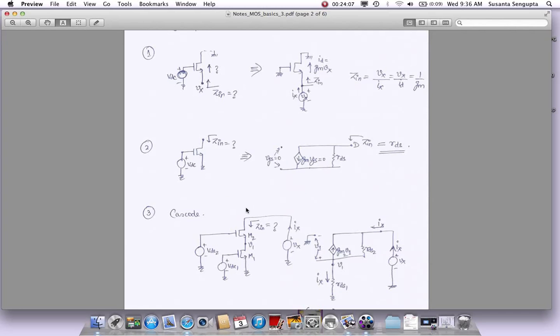So for example, if there was 100 millivolt swing here at this point, the drain, all this 100 millivolt will fall across this, and this current will change because of channel length modulation. If the gain of the stage is say 100, gm2 times rds2 is 100, and you have 100 millivolt swing, what is the swing here? It has transformed that 100 millivolts into 1 millivolt because it's divided by the gain of the stage.